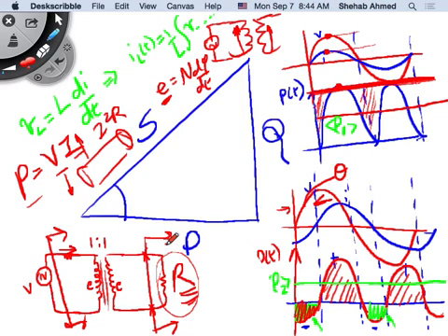When you have a transformer that has output terminals of 100 kilovolts, a 100 kilovolt transformer, if you remove the load, is the voltage going to change? The output voltage will be 100 kilovolts, whether or not you have a load. If you put a load in there, more current will flow. So you may have a small voltage drop due to the resistance of the circuit, right? But the amount of current that's being drawn here to create the magnetic field does not change.